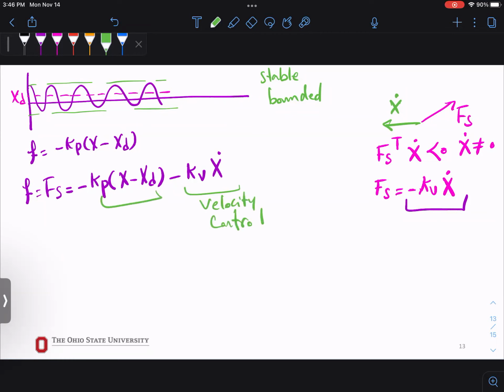This is your position control. Now we can ensure we get to our desired position and we will stop there. Now, if you remember our system dynamic, we said it is m x double dot. Depending on the system, because this is just a prismatic joint and we have one body, it's just m x double dot. But if you had multi-body, then you already know how to calculate the dynamic. So the left-hand side of your dynamic equation is the dynamic of the system, right?